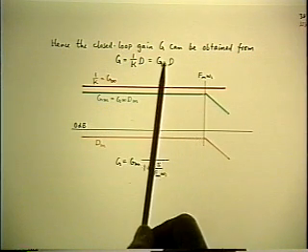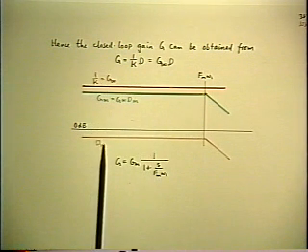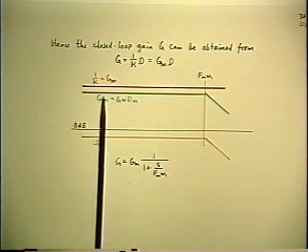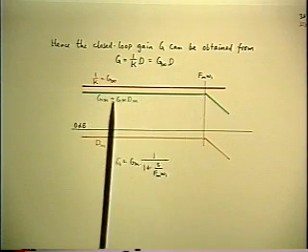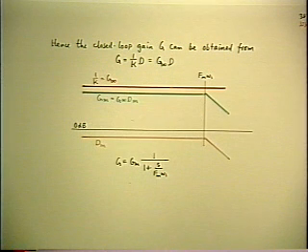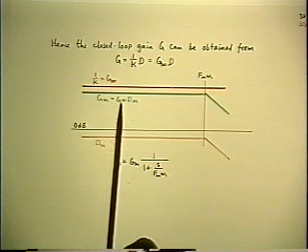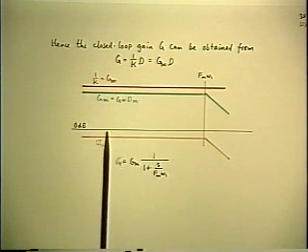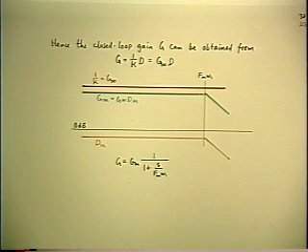All we have to do is multiply the two functions, which means a direct addition on the dB axis. And the sum of the red line and the orange line is the green line, and that's the final closed loop gain, which is G equals Gm, where the midband Gm is G infinity times Dm, and it has the same corner frequency that the D does.